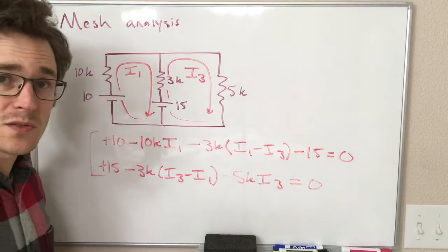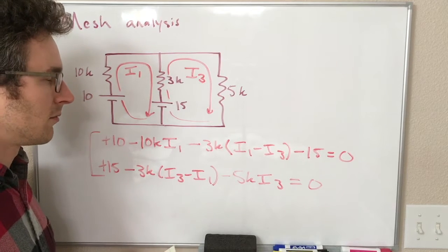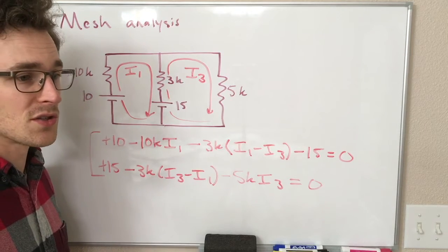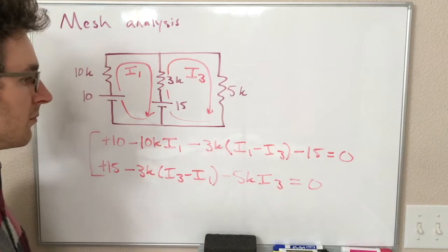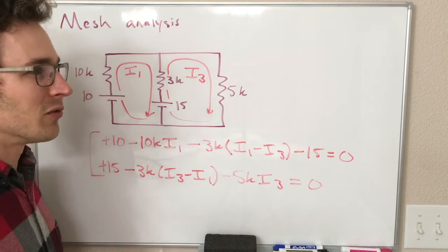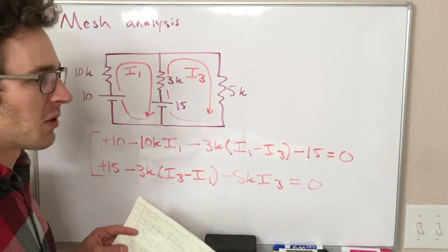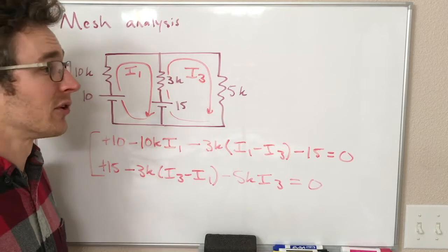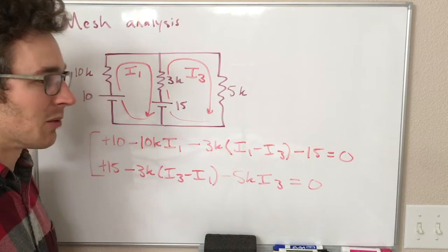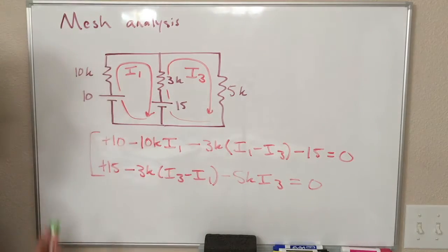For large circuits with lots of nodes, this can reduce the number of equations significantly. Solving linear equations does not scale linearly, so if you can reduce the number of equations by a factor of 1/2, you are speeding up that computation by a lot more than a factor of 2. So that's why mesh analysis is popular.